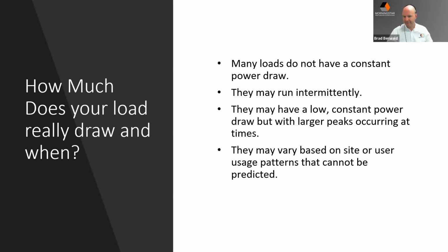the loads increase. They get pretty happy with that free energy, and they might add additional equipment, and that may be okay, but oftentimes it can complicate the system design because they've changed the equation at that point, and it can pose some problems. And if the system is no longer performing correctly, that often is something they look at: have they seen a specific change in the load, meaning that the power draw was increased and the battery and the array may not be able to keep up with it?